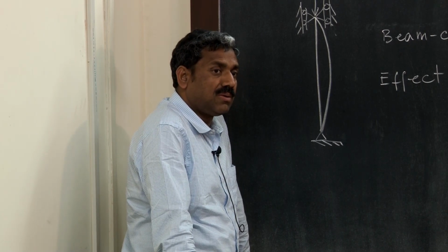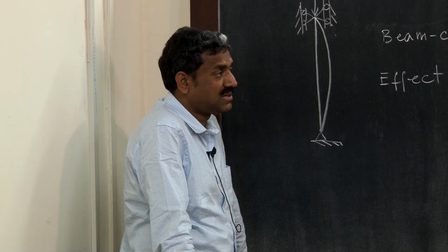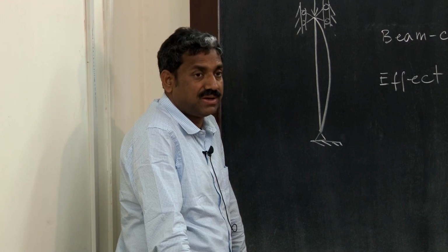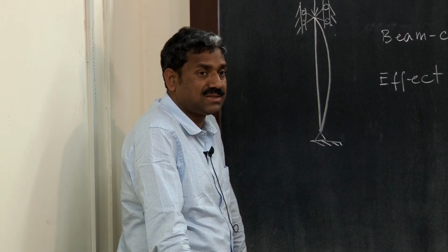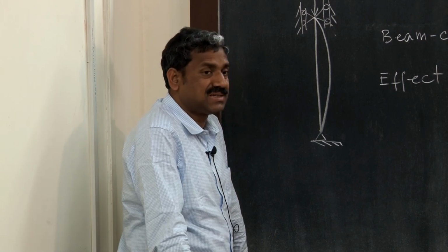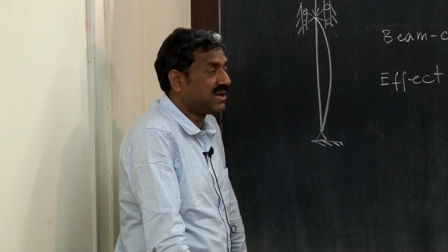Similarly, in plates you have thin plate theory, what you are learning in plates. Now, this is Kirchhoff plate theory, thin plate, where you neglect the shear deformation; the deformation is purely bending. So, plane sections remain plane after deformation, that is the assumption.